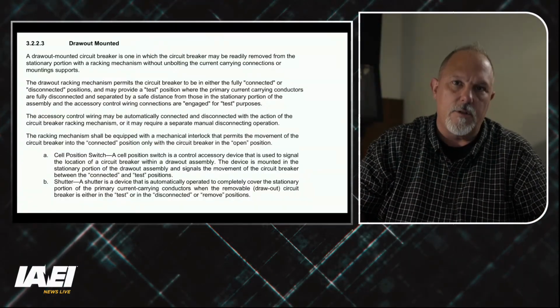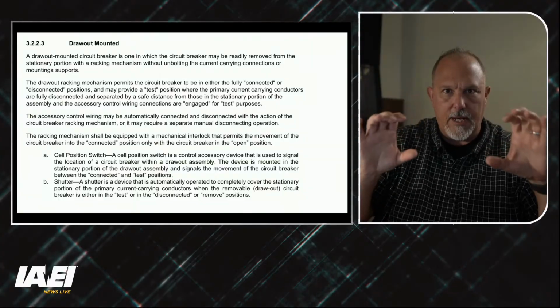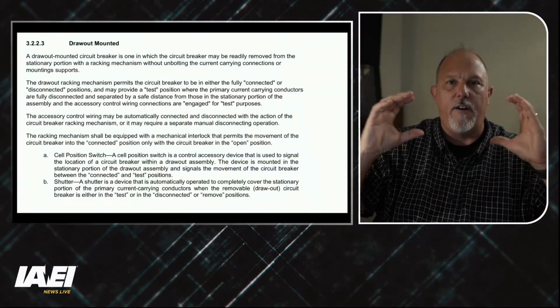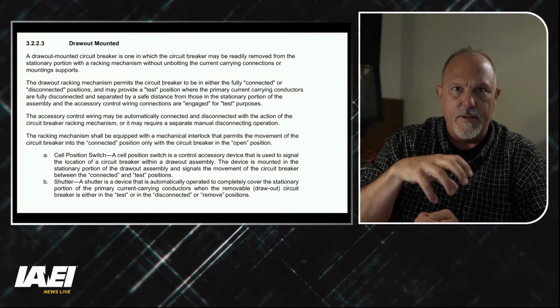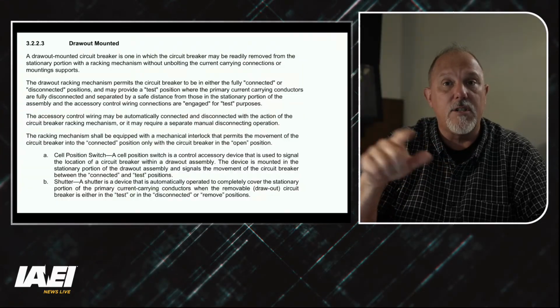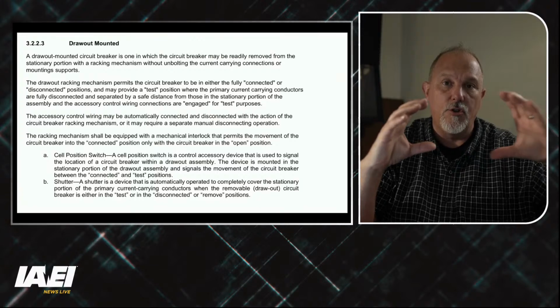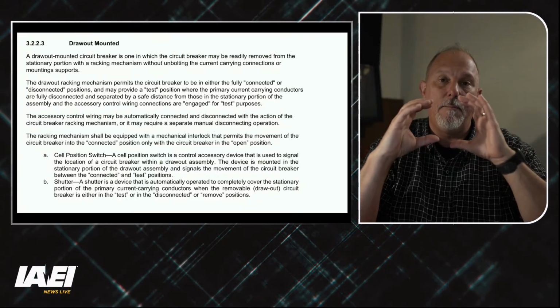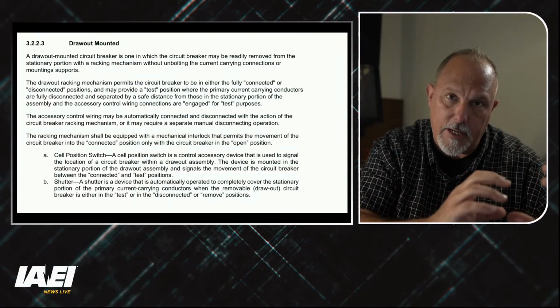Some manufacturers will take their breaker and put it in a cartridge where they bolt it in, and the cartridge itself slides in and off the bus. It's not necessarily the breaker itself. Okay? So in fact, there are some manufacturers that might sell a separate unit that goes on the line side to facilitate the marriage of that overcurrent device with whatever assembly you're putting it in.